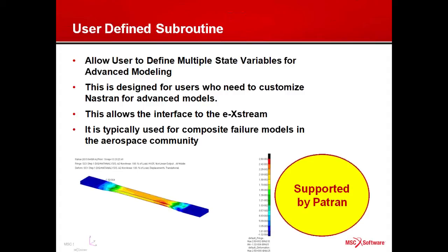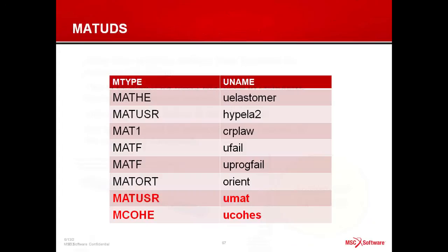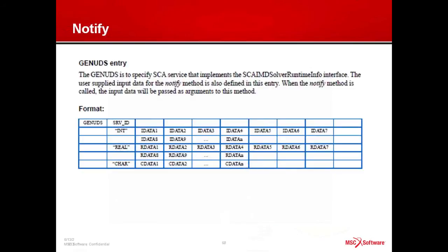So here was a little example. It's a uniaxial test specimen, and we load it up, and we noticed that the solution isn't exactly symmetric, and that had to do with the composite ply layout in this particular component. This is quickly, again, the two user subroutines that were used and the MSC Nastran options that are necessary to trigger the use of these user subroutines.